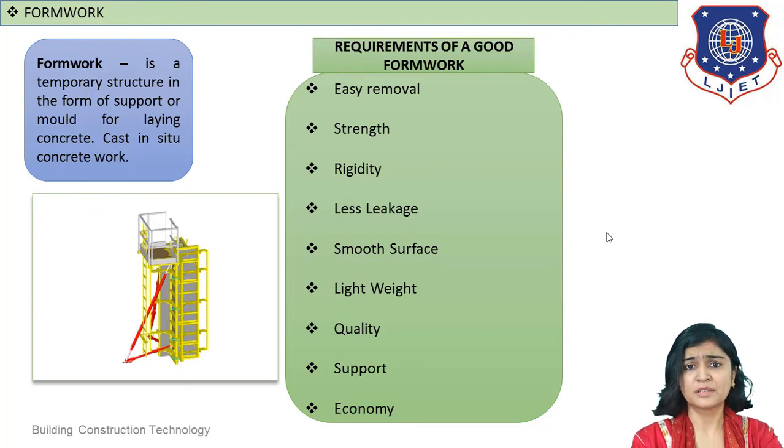Now, what happens is you have to remove this formwork. Let us say, generally after 24 to 48 hours, you have to remove it. When you are removing this formwork, there may be chances that your already constructed concrete member may get damaged. In some cases, you might have to apply some force to remove the formwork. So in this case, your formwork may also get damaged, and if it gets damaged, you may not be able to reuse it again. If you are not able to reuse it, then you will have an impact on the economy. So easy removal of formwork is your first requirement.